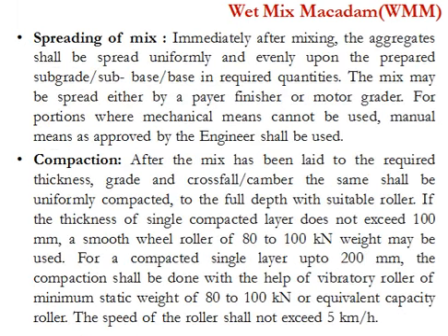So after preparation of mix, the next stage or the next process is spreading of mix. Immediately after mixing, the aggregates shall be spread uniformly and evenly upon the prepared subgrade, subbase or base in required quantities. The mix may be spread either by paver finisher or motor grader. For portions where mechanical means cannot be used, manual means as approved by the engineer shall be used.